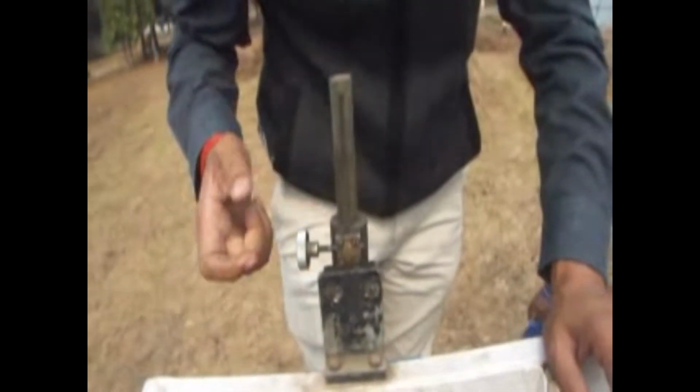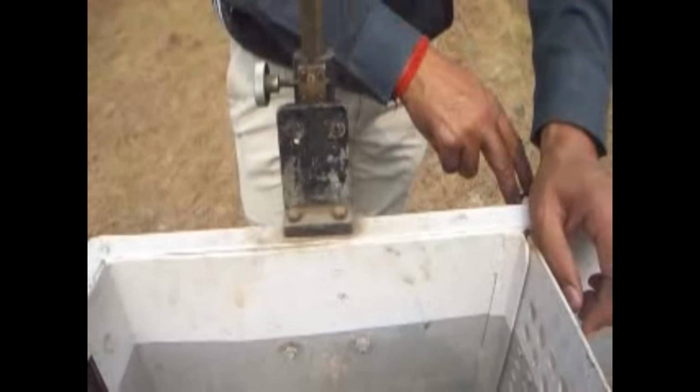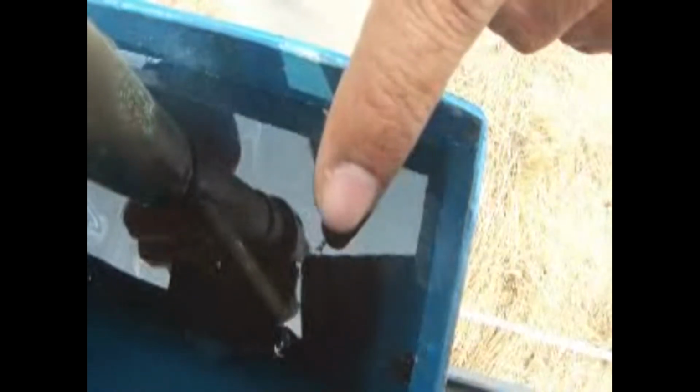And flow is measured by using a hook gauge. You can see we have a hook here. I will show you by putting the camera from that side. The hook is there, you just see it's a hook above the water. Now it is going, so this is the point where water is just touching the tip of the hook, and we can read the scale.